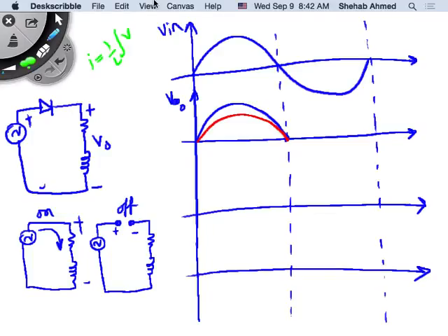There will be a delay because, again, current rises through the inductor because of this equation. Because of the physics of the inductor, it will take time for the current to rise through the inductor, right? So there will be a delay. It looks like this, and then the rise will be of an exponential shape because of the RL circuit and the first order differential equation, right? So it will rise exponentially, and then what happens?